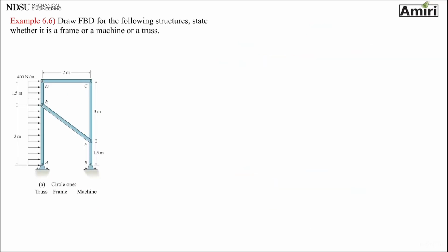This also looks kind of like a truss, but if you look at this member AD, there is a distributed load on it. So if we take the area of this load and put it at the center of the area, we're going to have something like this, F1. Now you see the force is not only at the pin, and that makes this structure a frame. Once it's a frame,